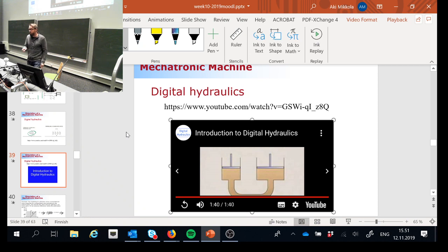So it's on. Okay, so your question is why it is not used. Well, it is actually being used more and more all the time. There are some difficulties associated with that because, like it says, digital means that it's on and off. And if you don't have a lot of these digital valves, it can make your motion choppy. Because once you open one unit, it can introduce significant changes in direction. So it can lead to the cylinder not moving steadily, but moving a little bit with steps. So that's one challenge, but it's still doable.